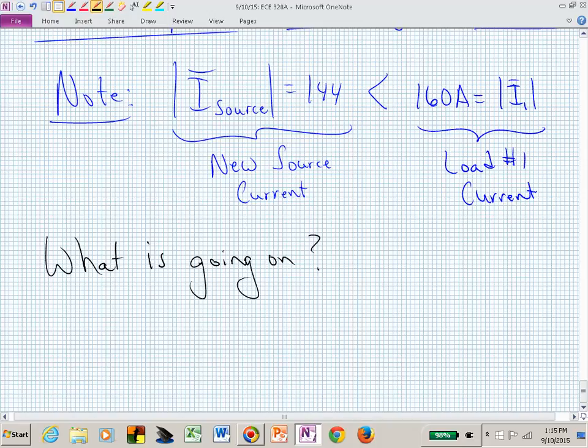What's actually happening is this sharing or exchanging of magnetizing VARs between the capacitor, or capacitors, because load 2 was capacitive, and we introduced a capacitor, and the inductive behavior of load 1. They're playing locally, and the source doesn't have to worry about what they're trading back and forth at the load side of that transmission line.